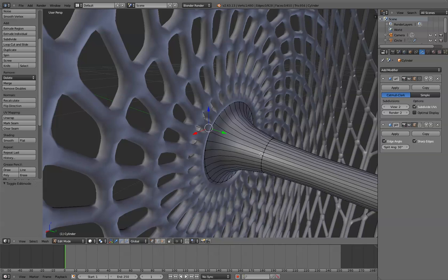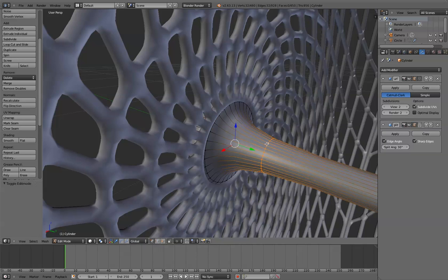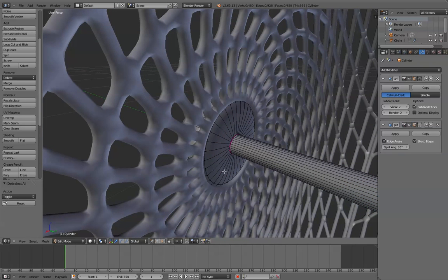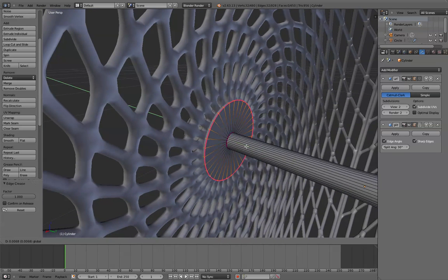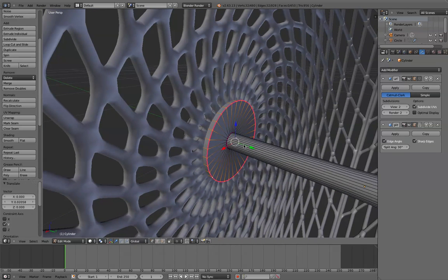And this just allows us, none of our verts are hidden in this mode, and they kind of shrink wrap to the subsurfed model. So again, Shift E to edge crease, and just Alt click to select edge loop, and then again Shift E to edge crease, maybe move that back a little bit.